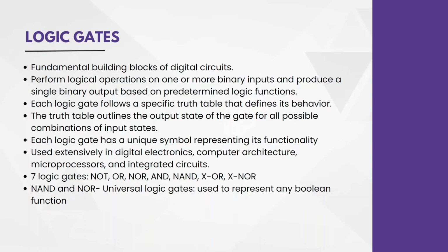Next, we have the logic gates. So logic gates are more like a building block in any digital circuit. And as the name says, it will perform some logical operation and it will give an output based on the inputs. So input can either be 0 or it can be 1. 0 we consider as low, 1 we consider as high, and based on the gate and the logic operation it performs, it will give an output that is again 0 or 1, or high or low.